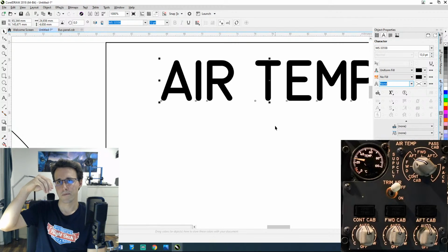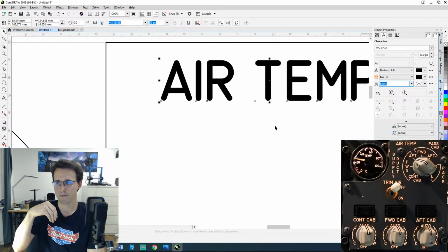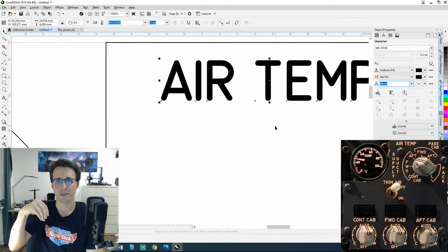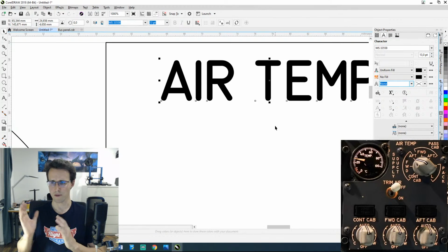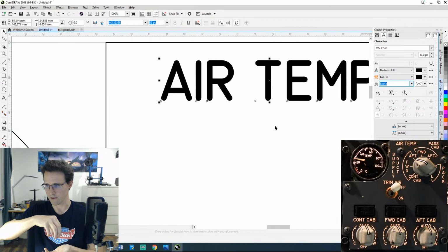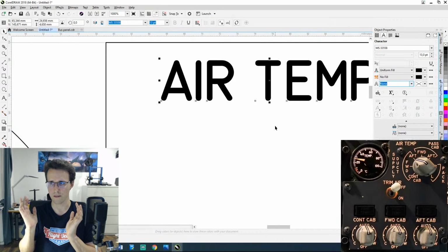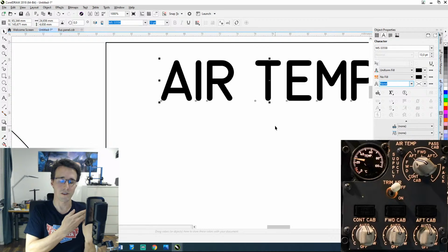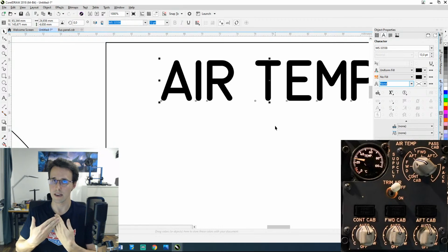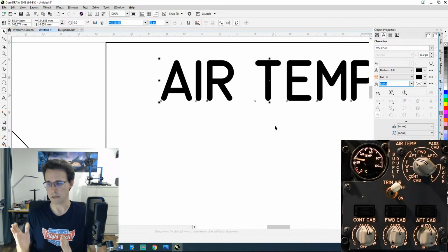And because my engraving bit went deeper into the material, the font became a little bit bigger. I thought this wouldn't happen because the program calculates the engraving depth and the angle of the engraving tool. Yeah, but it didn't, I think. So the fonts, when they came out on the panel, looked as I wanted them to have. Lucky me.